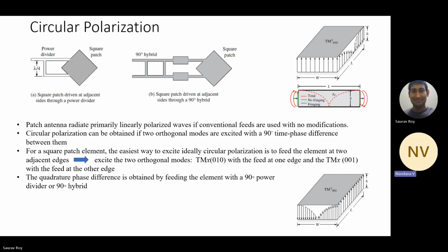This is a square patch, no? A square patch and a rectangular patch will be different, no? For a square patch, it does not matter much, only the frequency will be like this. Even that thing is crucial: if your length and width are not the same, the excitation of the E and H fields will not be the same.